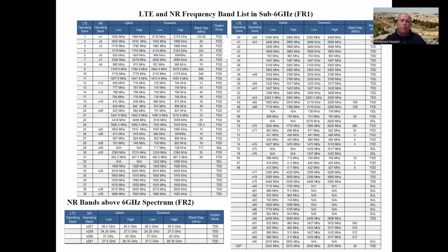For FR2, without any frequency translation, of course, any frequency down conversion, you need to move up to one of the ones that do 12 gigasamples per second, and those have 3 dB bandwidth on the order of more than 30 gigahertz. Of course, the signal to noise ratio and the effective number of bits is not as good as the lower ones, but in the next sessions we will look at that closer.